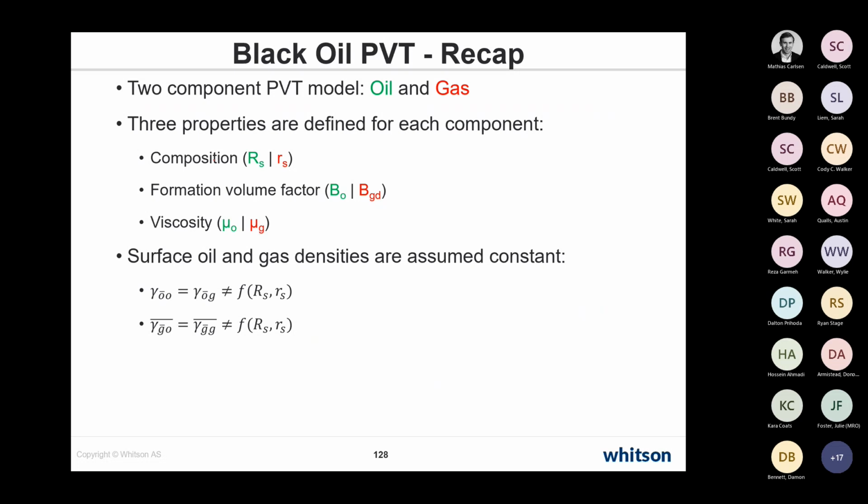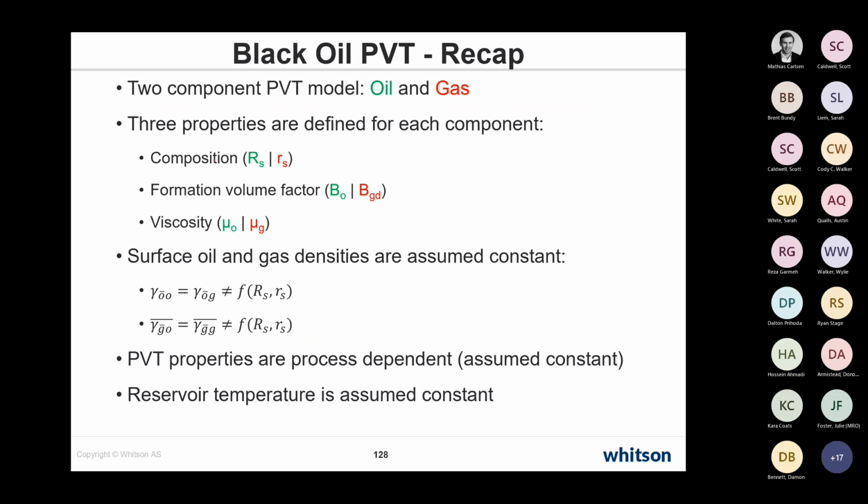Is it a good assumption? Yes, it's a really good assumption. It seems to work very, very well. And if you're creating PVT tables from an equation of state and you do that consistently, at least for primary depletion, you'll get virtually the same results as if you ran that model compositionally. The only times you will need to run it compositionally would be for gas injection or compositionally sensitive processes. And the last thing is that the PVT properties are process dependent, and of course you're assuming that the temperature is constant when you create a table. So if you use tables, for instance, for pipe flow calculations where the temperatures are different, you actually need to create a series of different tables that you interpolate within.